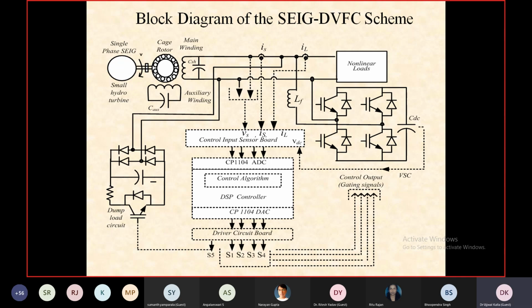But if the waveform of the generator is distorted, and we have implemented an indirect control, your power factor may not be unity in any case. So that is why it is very much important that there should not be any harmonics in the voltage waveform of the generator, the system, for proper functioning of the indirect control based scheme.